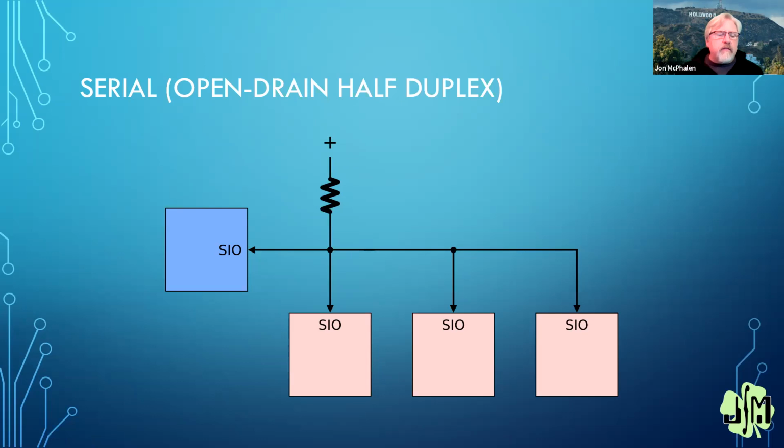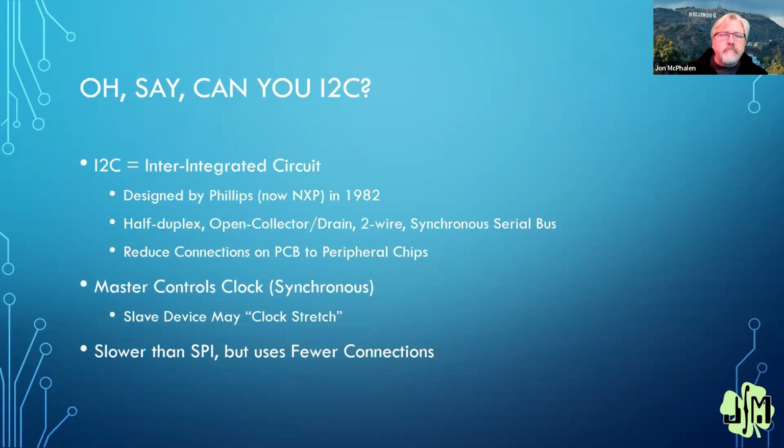The naming conventions inside the P2 are really nice, because you have pin high, pin low, and pin float. Pin float is what releases that pin. So if you have a bunch of devices that want to talk together over a short distance, that's a really good scheme, over one wire.